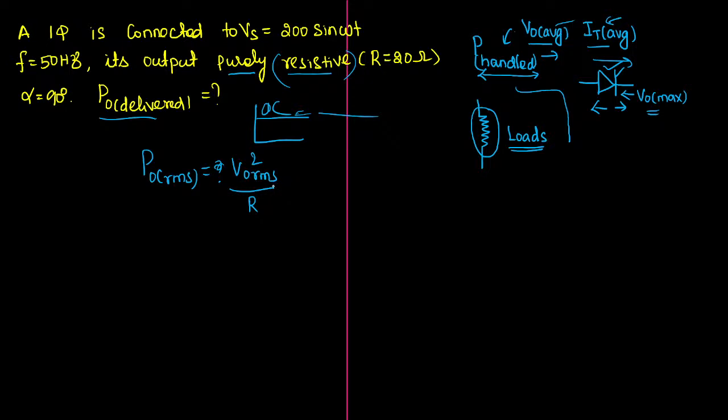Remember? So what new things have we learned in the full converter? First thing, I have already told you, your output current will become ripple free. Yes, this could be possible when I have told the point. If the question gives no data about load or output current, neither load nor output current, then by default you can assume your current will be ripple free, continuous current. One case.